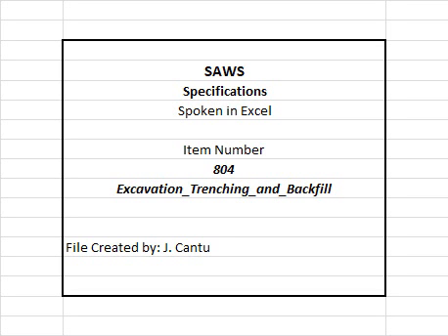I. Upon completion of the dewatering work, the contractor shall remove all equipment and leave the construction area in a neat, clean condition that is acceptable to the inspector. J. The contractor shall maintain a groundwater table at least 12 inches below the finished excavated trench depth. K. Performance of the dewatering system for lowering groundwater shall be measured by observation wells or piezometers installed in conjunction with the dewatering system, and these shall be documented at least daily.